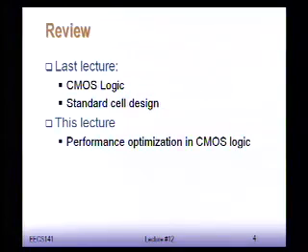So, for instance, in processors, ALUs, and really high-performance blocks, people really go in and design every transistor individually. But for a lot of applications, this has a very long design time. And for a lot of applications, you are willing to trade off design time for worse performance or worse power. In other words, you say, I'm willing to tolerate a slightly lower performance or a slightly higher power, but I don't want to have to design every transistor. And this is where the standard cells come into the picture.